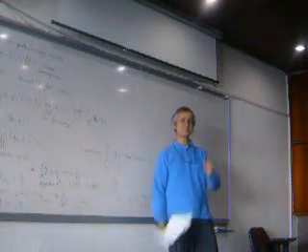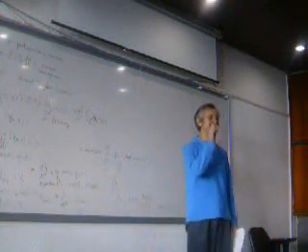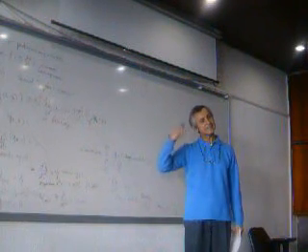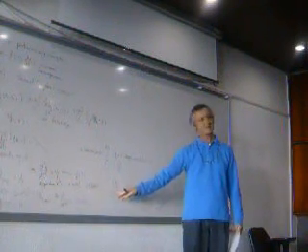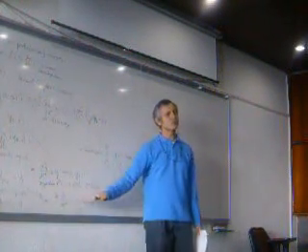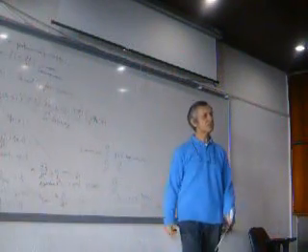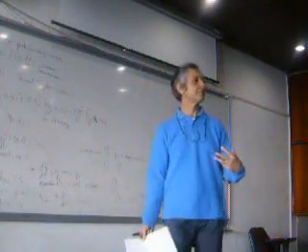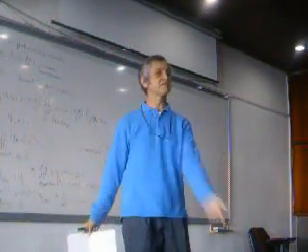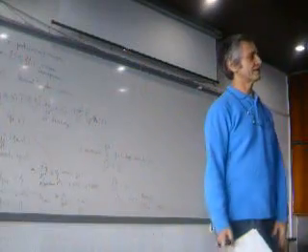Because if it's so borderline stable, and if my linearization creates an epsilon error, I may get that perhaps in a slightly modified, slightly disturbed version of the model, I may get a small positive real root here. So in general, the borderline stable result, as a result of a linearization of a nonlinear system, gives you a weak result.